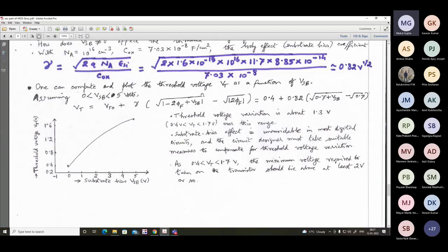In general, we are considering the n-channel transistor. So for this, source is at positive potential with respect to body. So then this will involve the total expression. The generalized expression will involve the presence of the zero bias threshold voltage and gamma, that means the substrate bias coefficient. We have to consider this sub-expression, that you have to keep in mind. Now, VSB, the source-substrate bias potential, can vary over the range 0 to 5 volt.